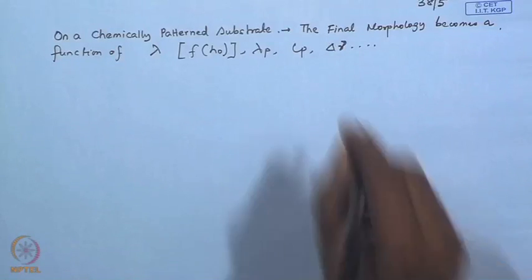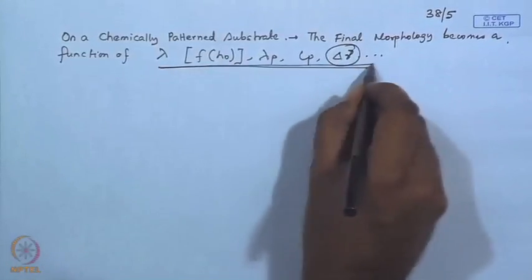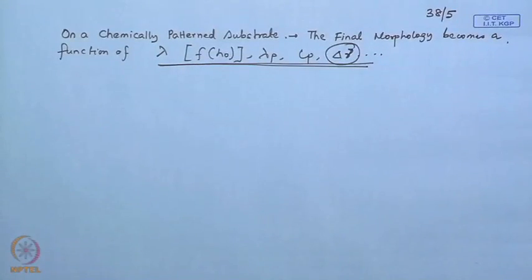You can use the same pattern substrate, but with different delta gamma, you can get to different structures. So, these are the advantages. Unlike top down soft lithography, where every time you want to create a new structure you have to have a different stamp, you can really rule that out and tailor or play around with the parameters, and you can get to a whole lot of things.